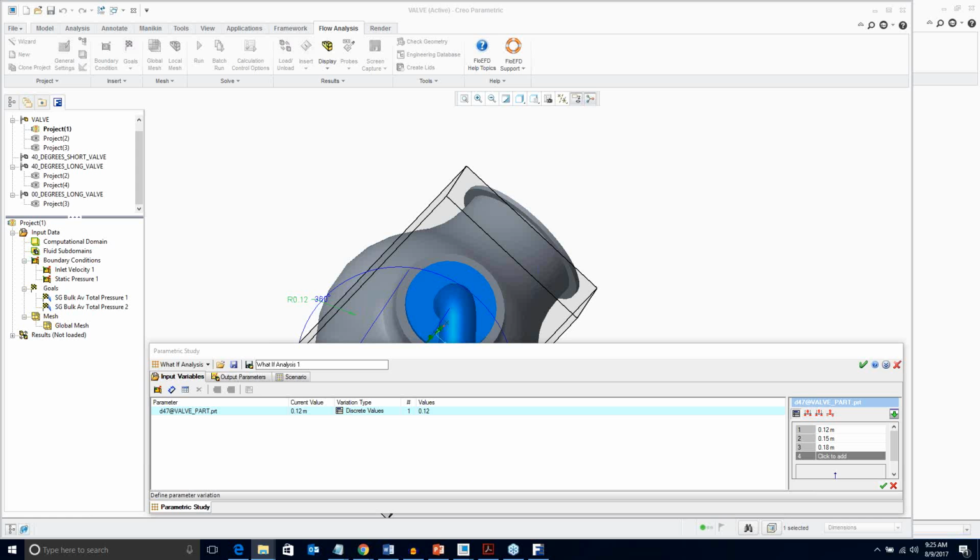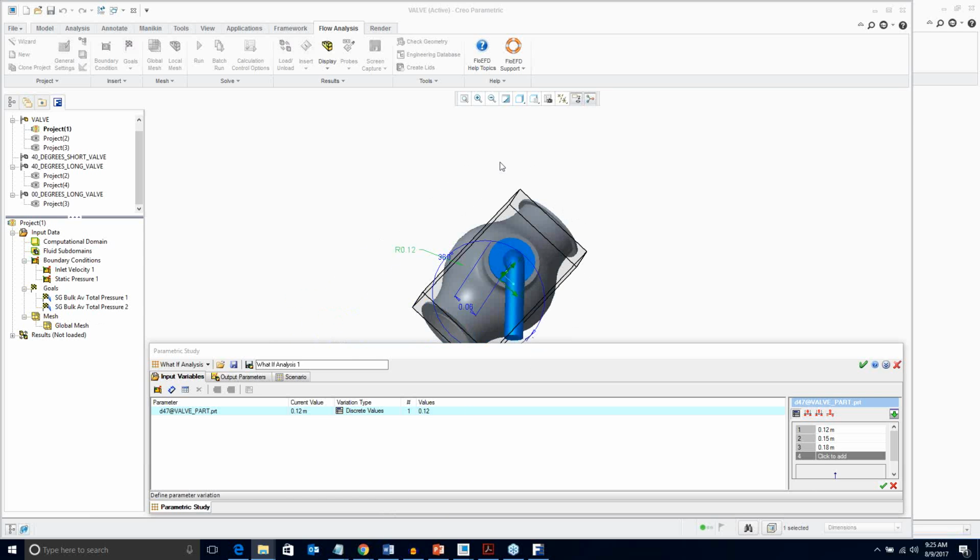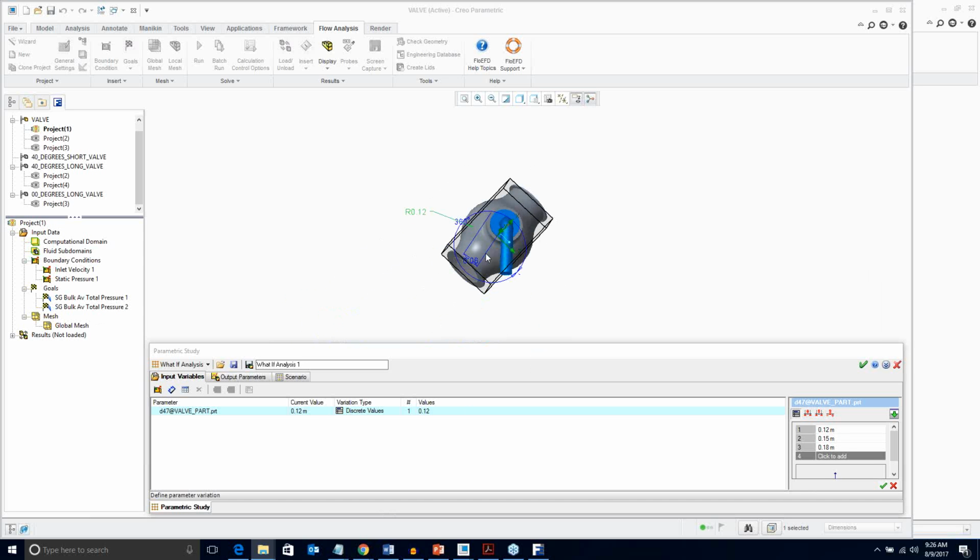How did you know to make the output port longer to solve the vorticity issue? I don't want to say common knowledge in CFD, but in general with CFD, vorticity could influence your inlet or your outlet, and extending your inlet or outlet regions 5 or 10 times the characteristic length of your model is preferable.